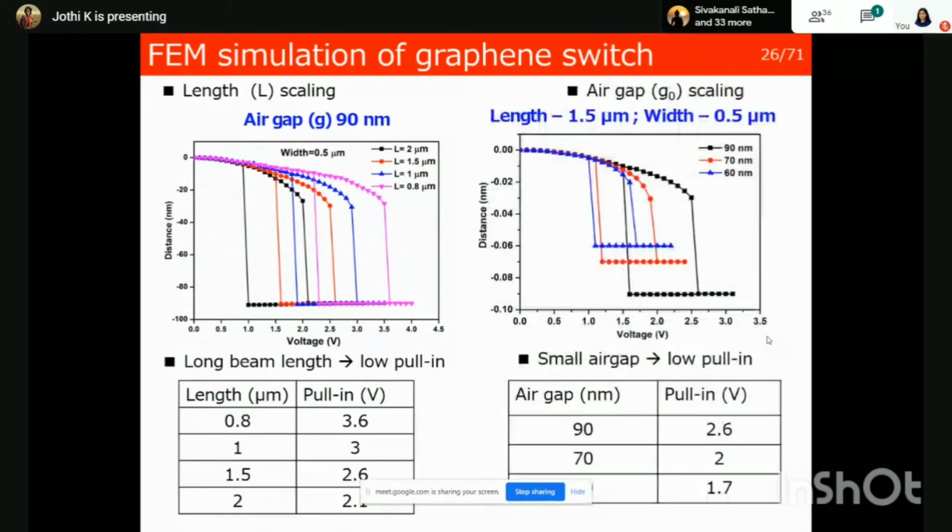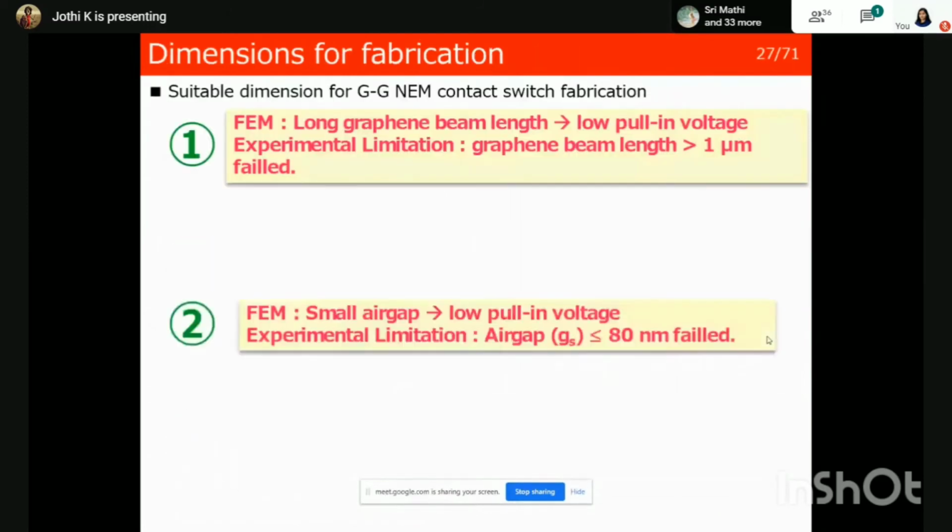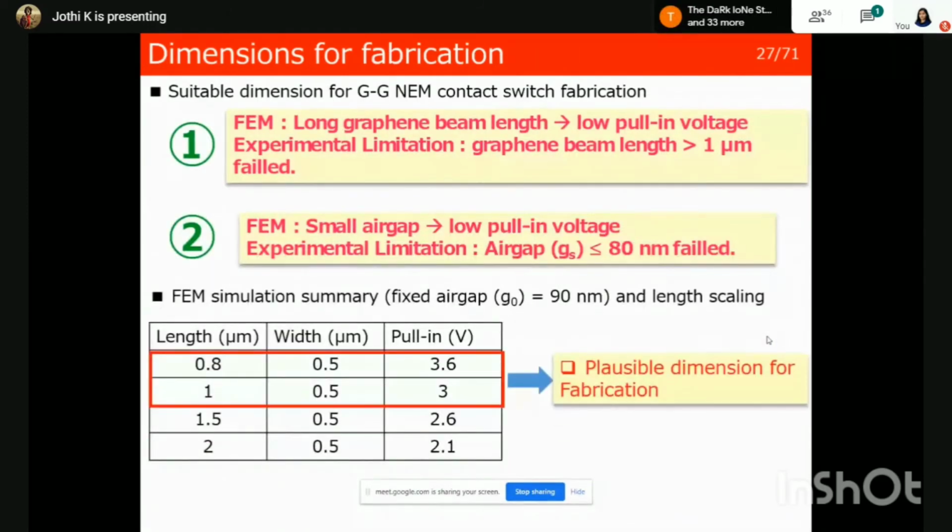If anyone is interested in FEM simulation for graphene, that is again another hard problem. Nobody did FEM simulation for 2-dimensional materials because all finite element method simulations are really intended for 3D materials. There are no actual 2D things. There will be a lot of problems whether you do it in COMSOL, IntelliSuite, MEMS Plus, Coventor, wherever you go. If you want to do 2D materials, especially graphene and other materials, there is a lot of problem even choosing the right property values to analyze the results.